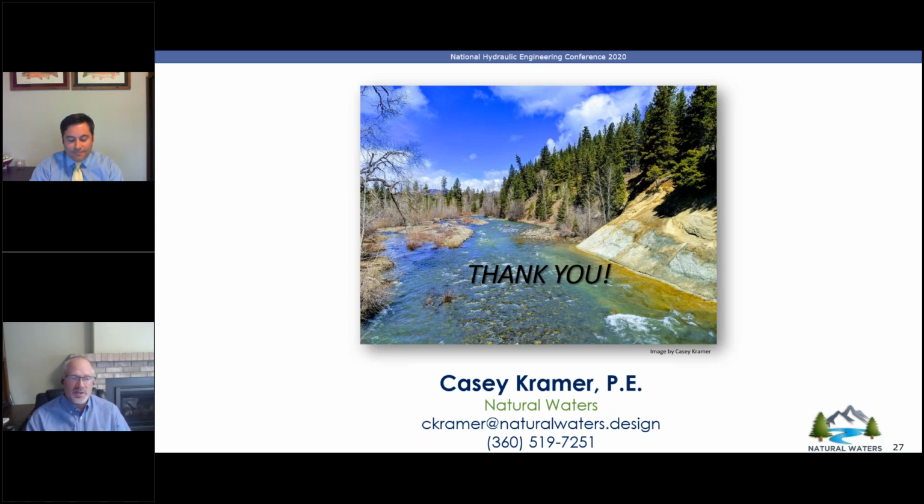Now, that being said, it doesn't mean that HEC-RAS 2D can't be used, or other models, but there's certainly things that RAS 2D is not set up well for now. It can't do pressure flow. I've seen more than half a dozen ways to model piers in HEC-RAS 2D, and HEC is still a little quiet about what the correct method is.